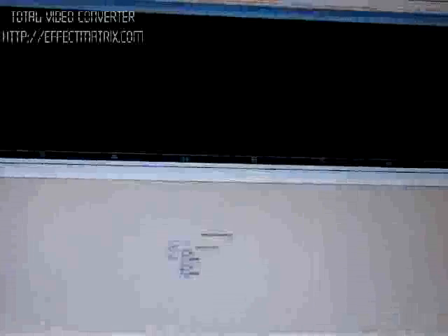We have to paste this file into the LTSpice program files, LTSpice library files, sub. We have to place all the library functions here. Let us paste just here. Now let us run this.